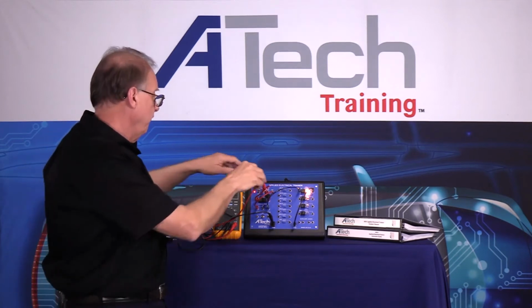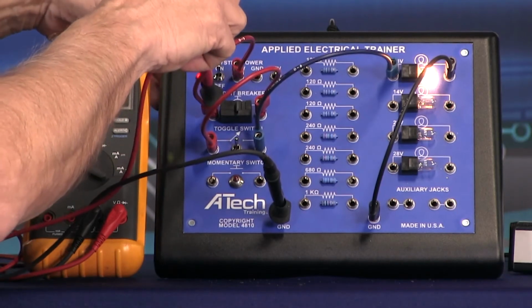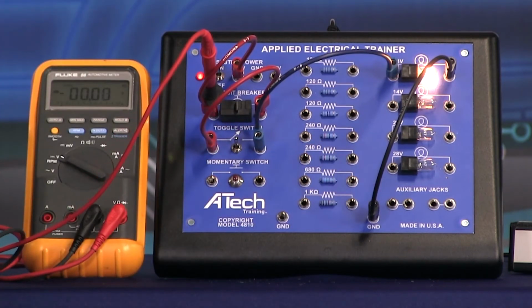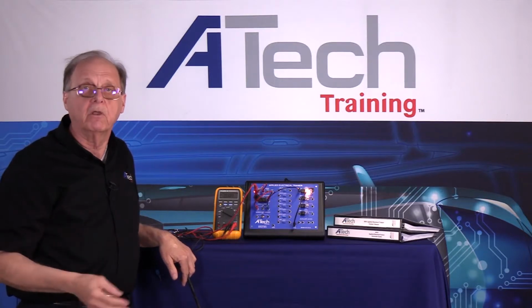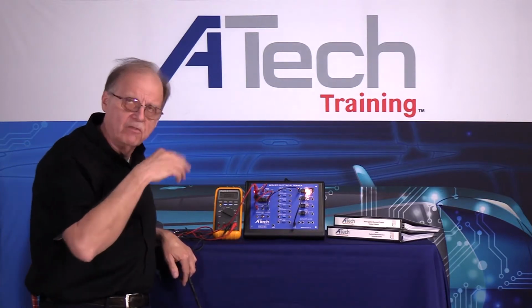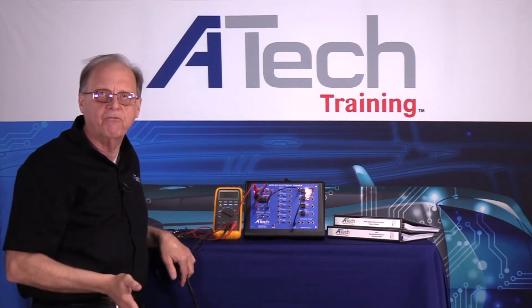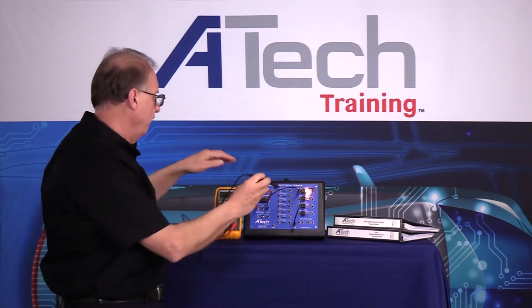So out of curiosity, I might want to do a voltage drop right off the bat. Again, I take my red lead and put it on the most positive side of the circuit, and I take my black lead and put it on the negative side of the circuit. Some of the instruction manuals on the factory tools that I've been looking at will call it B plus and B minus. Same thing. So I'm going to do this immediately.